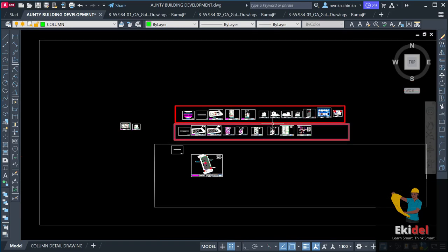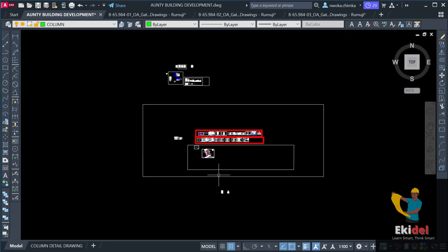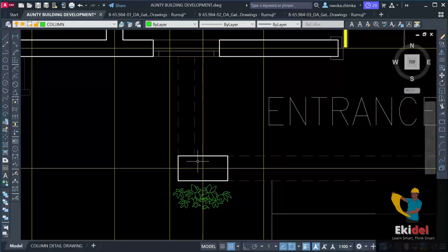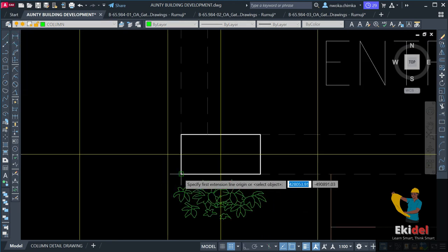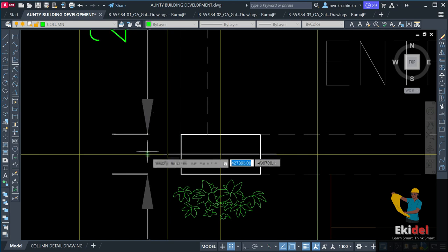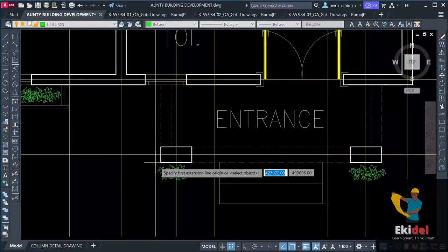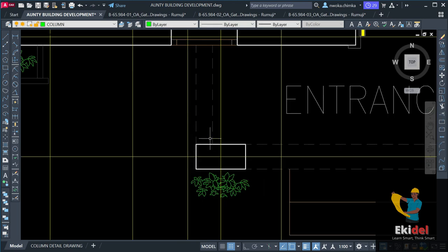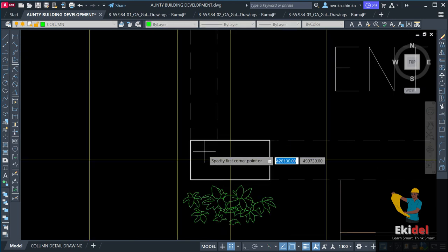So I'll go here and place on our GA drawing a column directly at the center, or two columns here and here, because placing this size of column might cost them a lot of money to cast. Okay, this is 225 by, let me see the size, oh okay, it's not that big, so I can use that and place a full column.